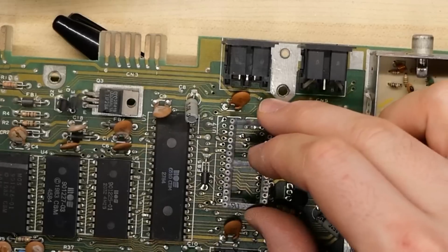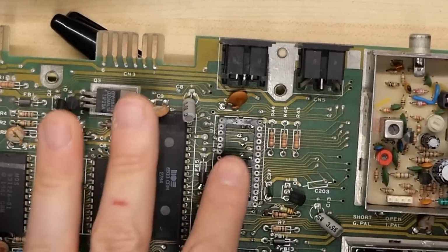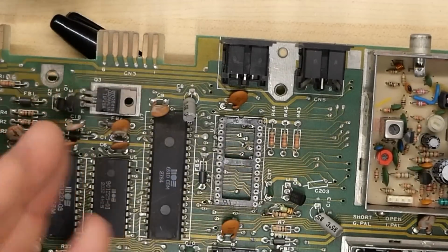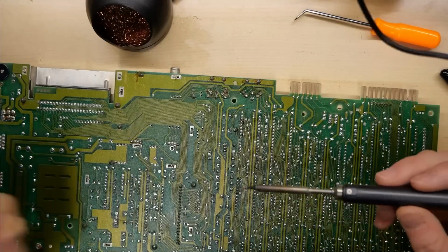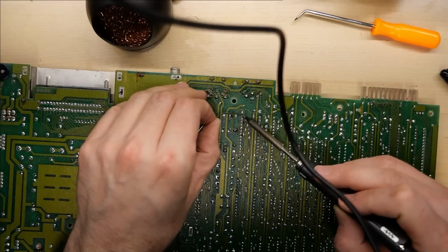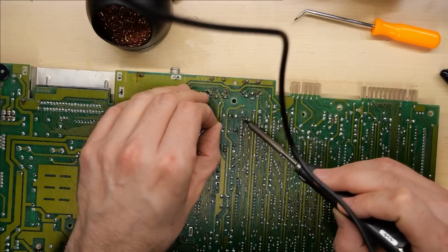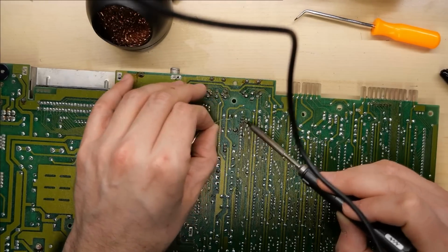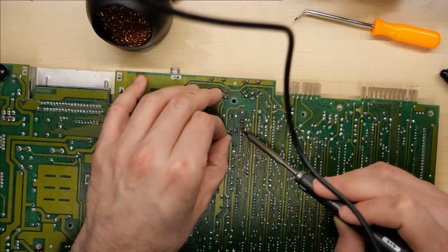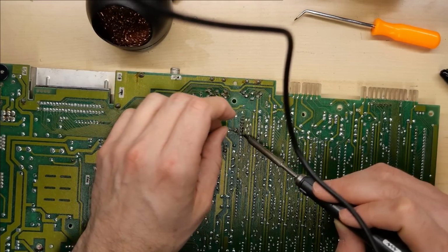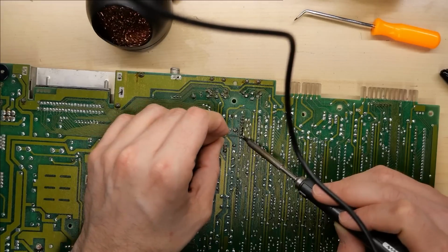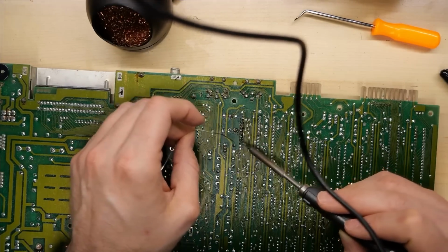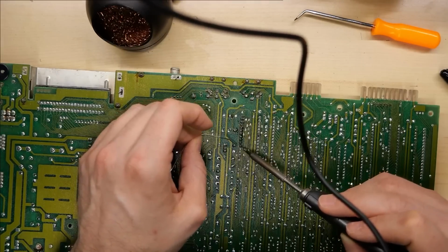And now it's just a matter of installing a new socket in place of the old one, like that. I'm gonna use one of these round holed ones. I prefer these over this type. They just seem a little bit more durable to me. And when you're installing a new socket like this, make sure you just solder 2 pins, 1 on each side first. Then you can make sure that the socket is flush with the motherboard by heating up that one joint and then pushing it from the underside. Make sure you don't burn your fingers because, of course, when you push on it, you don't want to push on the part you are soldering onto because that will get hot, obviously.